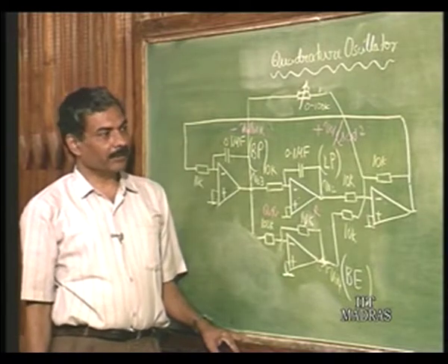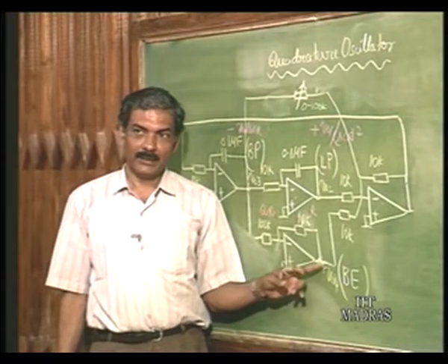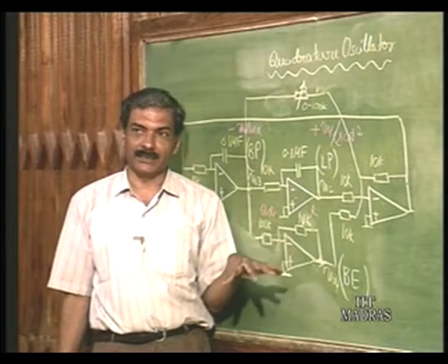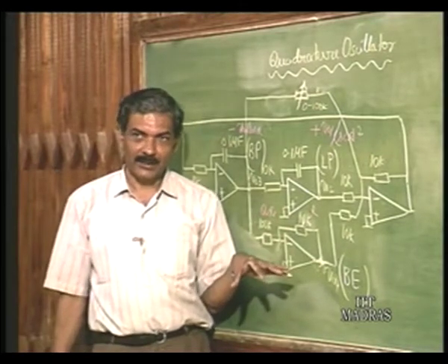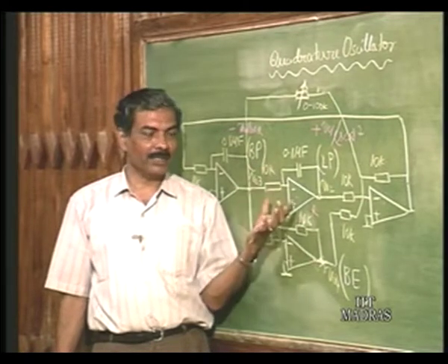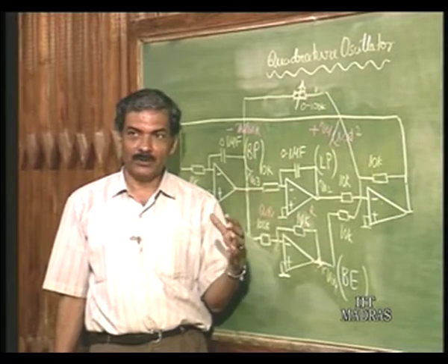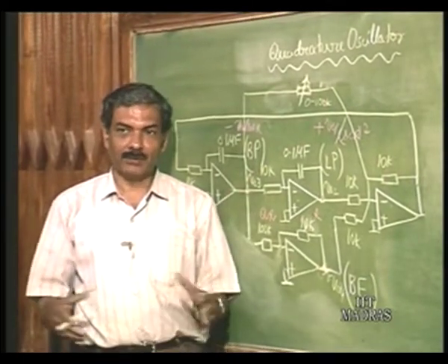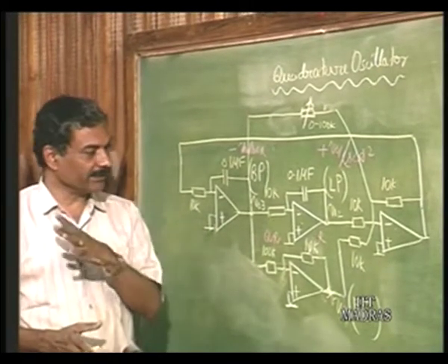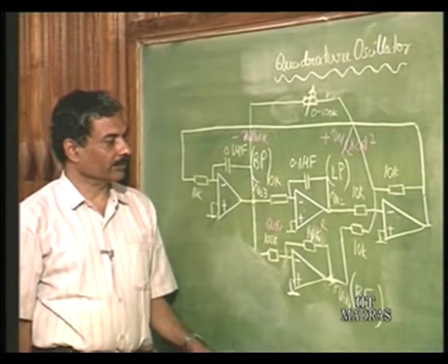I have to make only one comment. Last time when we saw the notch output, the notch output that we saw on demonstration has a phase inversion of 180 degrees. What I have drawn is without phase inversion, when the fundamental is removed from the square wave. What is shown is going to be the notch output without phase inversion. So, with phase inversion is what you really saw on the screen of your oscilloscope.